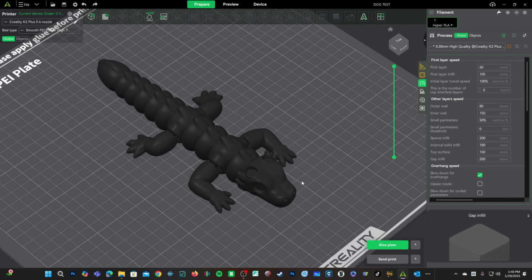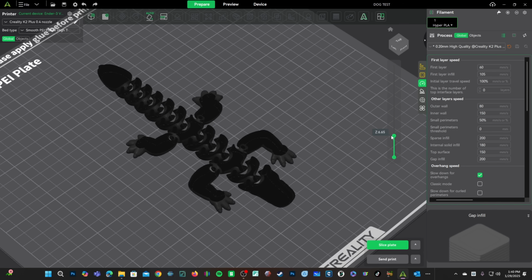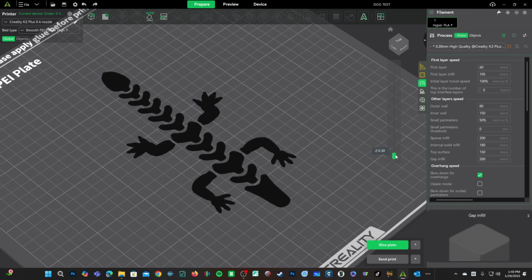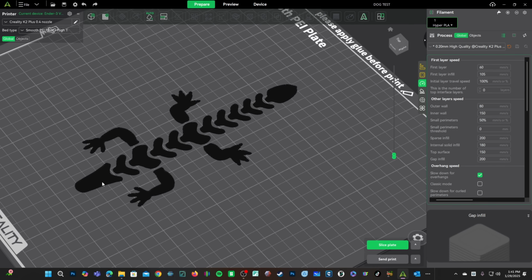Some models have very, very, very small initial bed contact and lots of little tiny parts that must successfully be printed for the entire model to succeed. And if even one of the tiny little details fails and is lifted off the print bed and tossed around, the whole model is a waste and you're going to have to start over. Therefore, printing the first layer and then the first infill over that layer should be done very carefully and slowly, because once it's successful, the chance of the following layers printing successfully is very good.